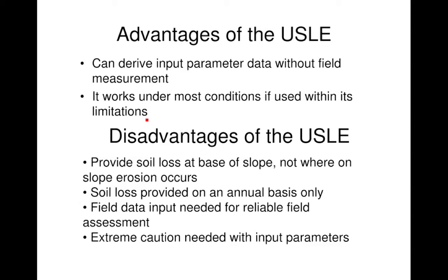Okay, you can't apply USLE if you haven't done your own field calibrations, right? And you should treat it with extreme caution when extending it beyond where your experimental data was derived from. You should treat it with extreme caution.